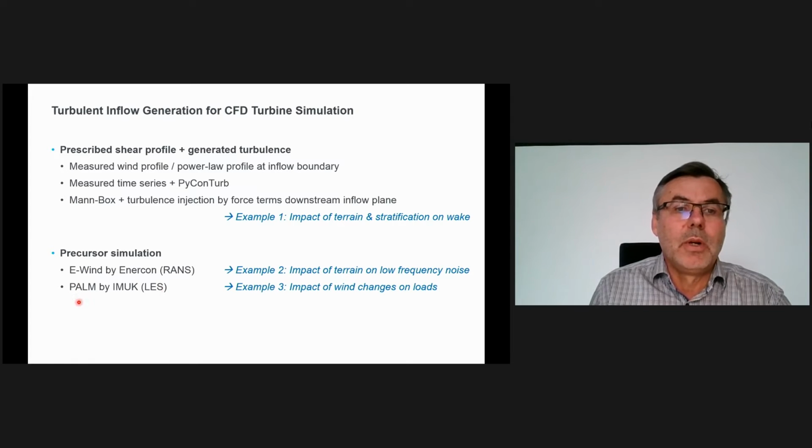Another option is to do scale resolved simulations, LES simulations. And here I have an example from the colleagues from Hanover. They develop and use the PALM code, the LES code, and we couple that to our CFD. And I will give you one short example, if time permits, on the impact of wind changes on the loads of a turbine with controller.